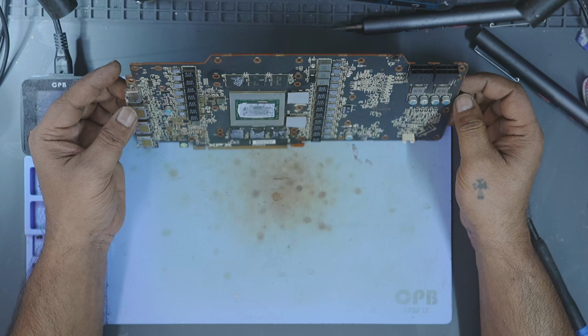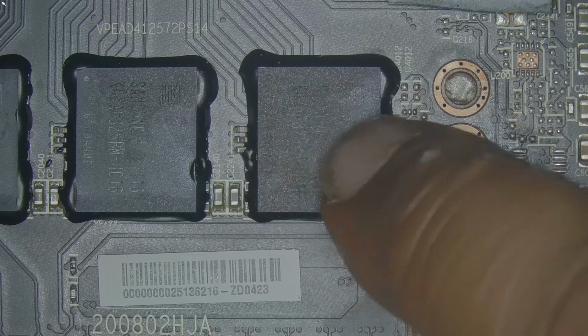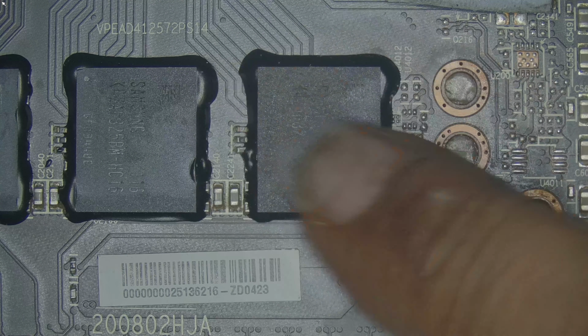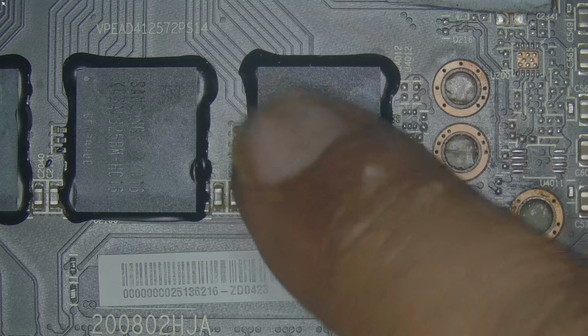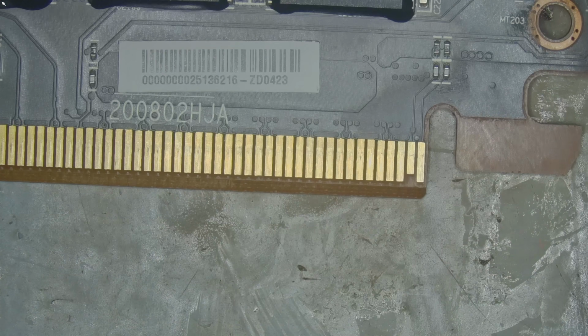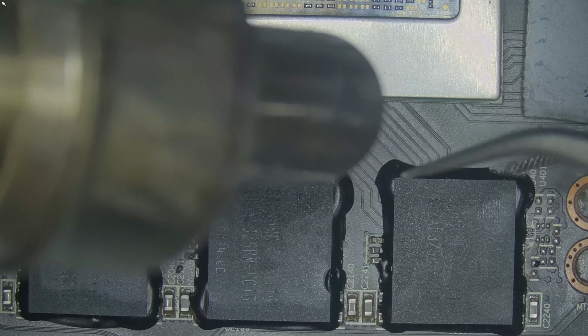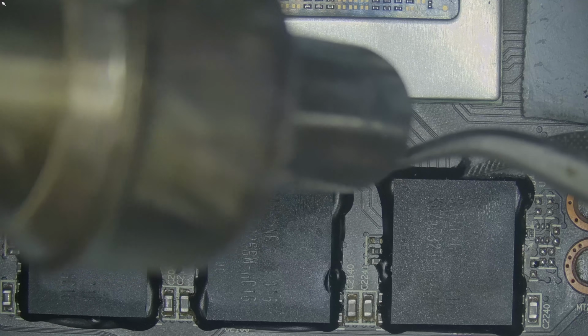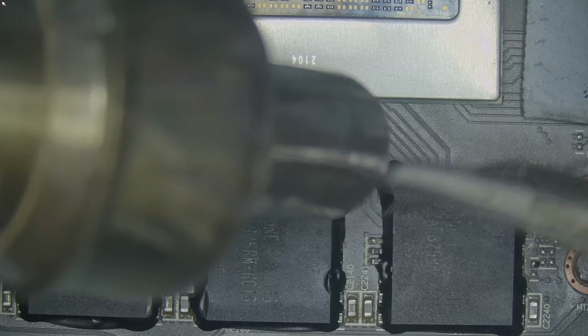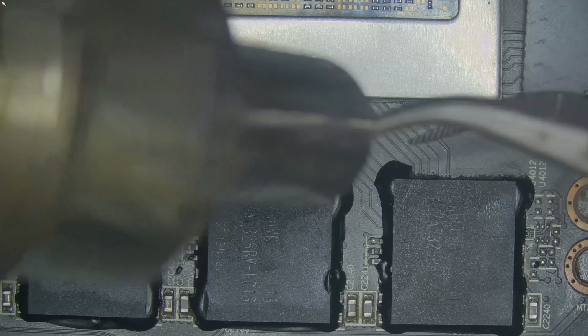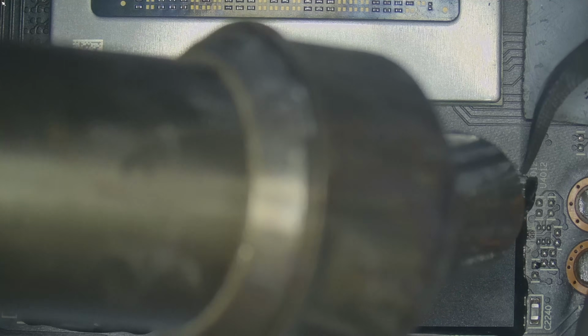With the cooler off, you can see that XFX has applied black epoxy around the bottom memory modules. The purpose of this epoxy is supposed to secure the memory in place so the contact with the PCB isn't broken. But here's the irony. This RX 6900 XT failed despite the epoxy. In my opinion, it's pretty useless. No matter what they apply, over time, the weight of these heavy GPUs, especially mounted horizontally, eventually causes contact issues anyways. And all the epoxy really does is make the repair process more difficult.